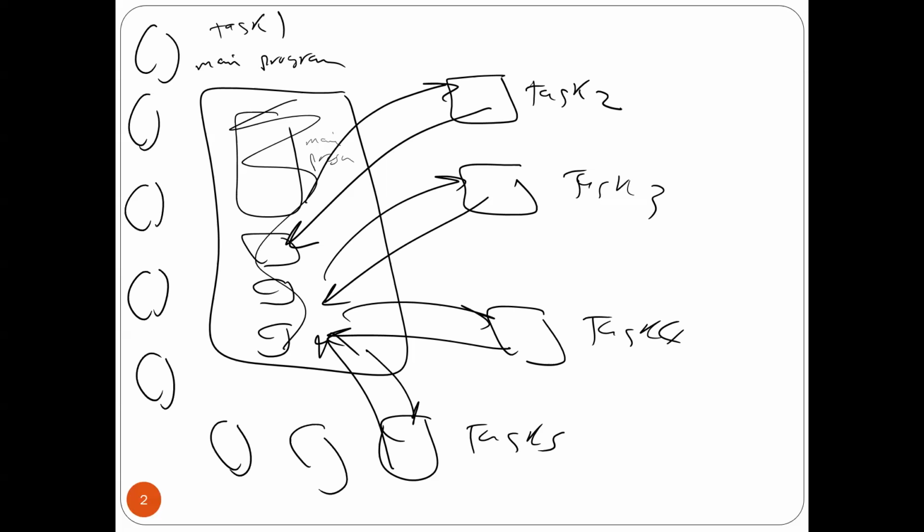So yes, if you use too many interrupts, more than the computation capability, it's going to work, but the program will start not responding. When you press a button on a keypad, it doesn't display at the same time. There is some delay. Why? Because the keypad was suspended and the system was doing something else. But again, if you do it very quickly, it should be okay. You can run many things at the same time. Any questions?